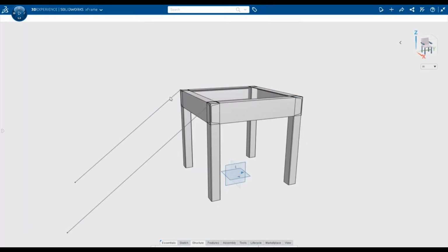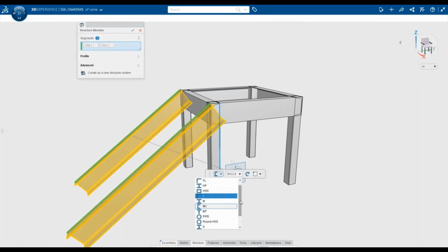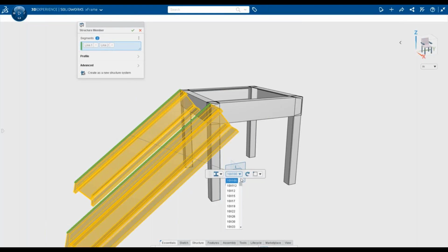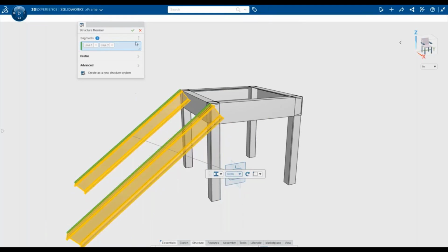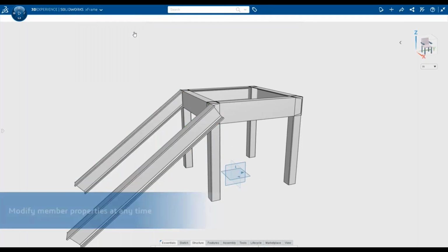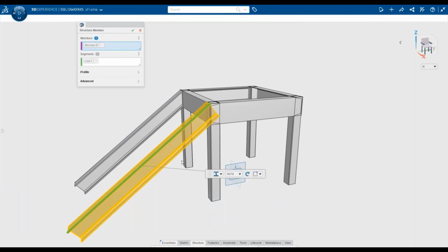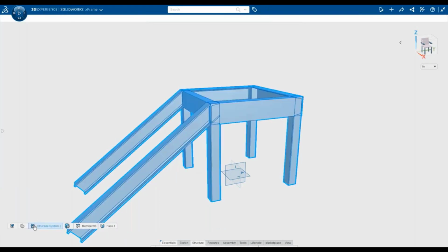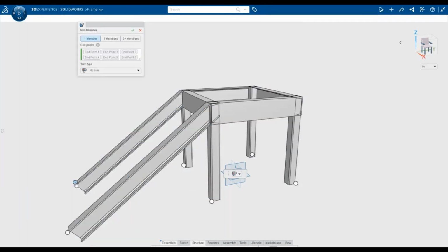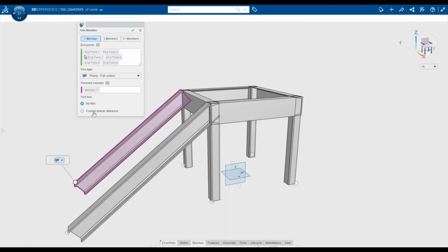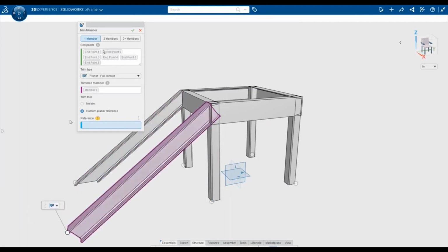So here once we've added a couple of members, primary, secondary members, we can set them, and based on which we can also create the trim sections with respect to these sections. So if I want to modify any section anytime, that can be done simply by going to that particular thing, double clicking on it. I can change the location. Here, if I want to trim a particular section, simply by selecting the primary members, what kind of contact I need, I can simply trim this with respect to a particular plane.